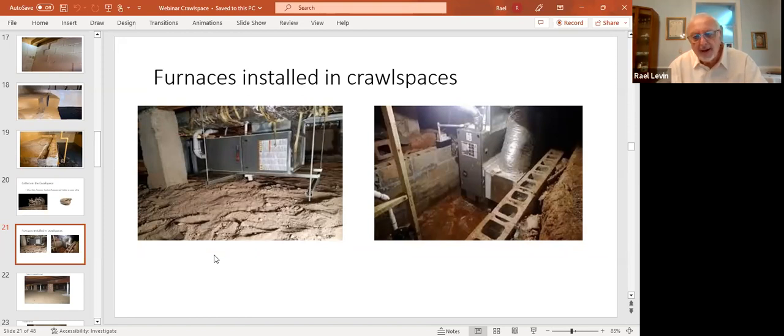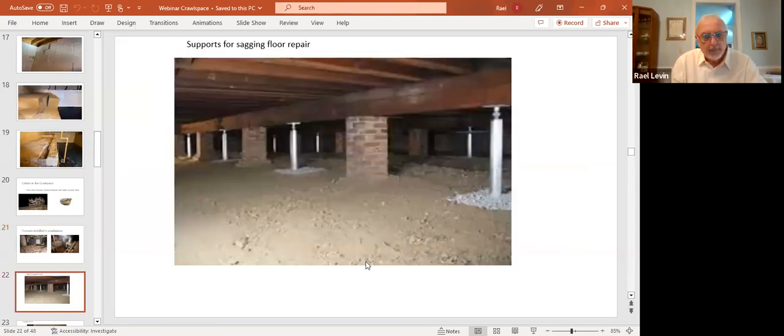So we need to do that at least 4 times a year, perhaps going with an electronic filter or a once-a-year filter might be a better idea and a recommendation for the buyer. But if you've got a standard filter in there, we'd want to make sure somebody would go in there and change it, or else you're going to shorten the life expectancy of the furnaces.